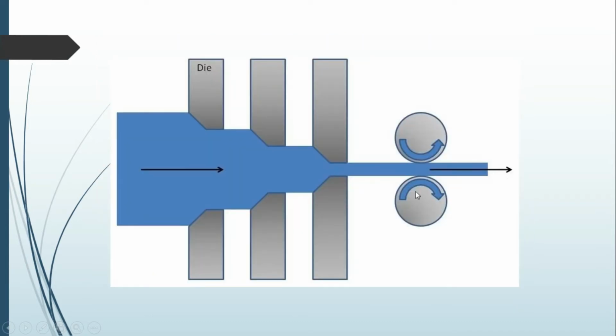Okay, so what about wire drawing and other things? Yes, if you have a certain amount of material, you have to pass it through some die, so that we will continuously get some reduction. Finally, the required dimension will be achieved. Within one attempt it is very difficult to achieve this much thickness. See, input is this much and output is this much thickness only. So it is necessary to apply these step reductions to get the required thickness. Don't worry, I will tell how the reduction is happening and why we are using 3 instead of 4. That we will discuss when we go for numerical problems.